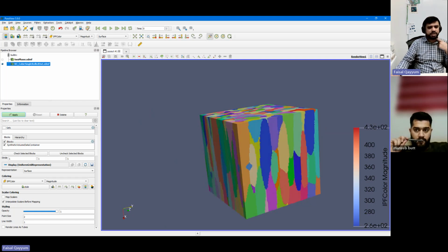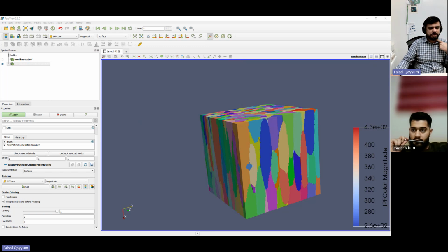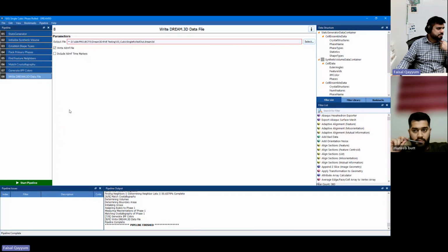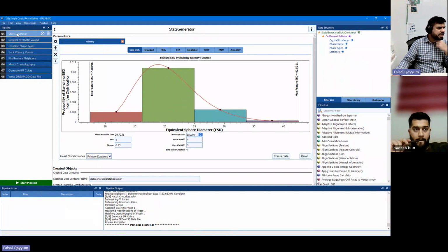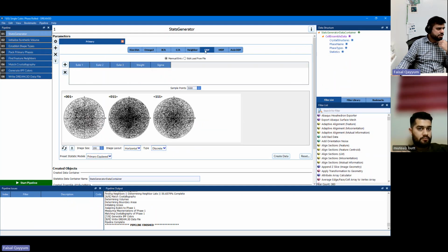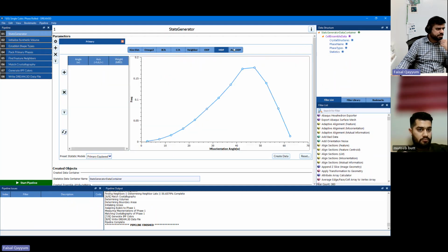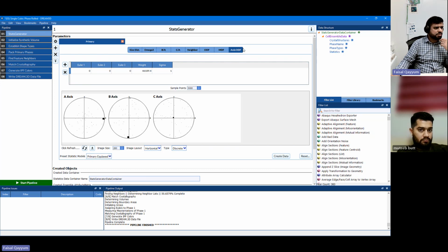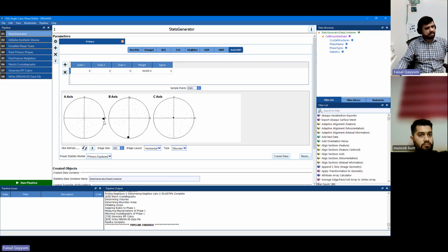So the idea is you can look at these examples and see what they're doing here. The orientation distribution function is the same, but you will see that the axis orientation distribution function is the one in which they have elongated the axis in the build direction, right? So in the x direction, all the grains are aligning in the x direction.